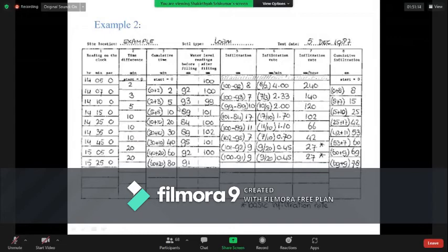So once you understand how they calculate each portion, then it's easy for you. First, with the stopwatch, they get the time interval and develop the cumulative time. Then from the drop in water level, they get the infiltration.